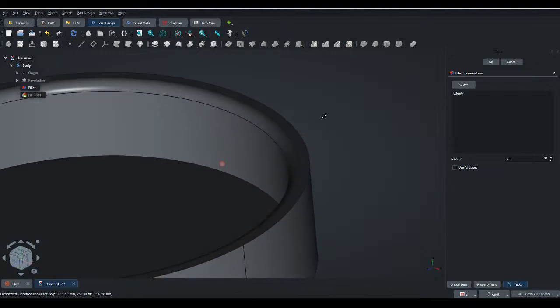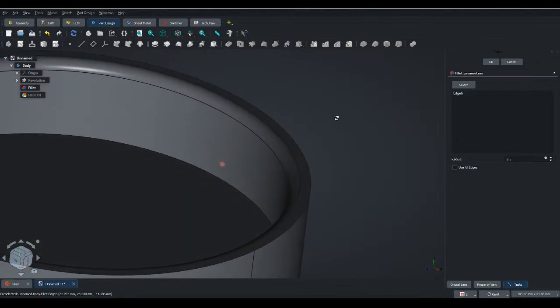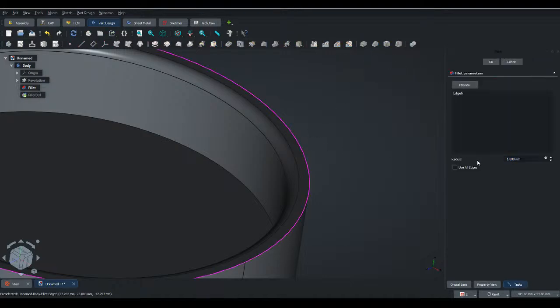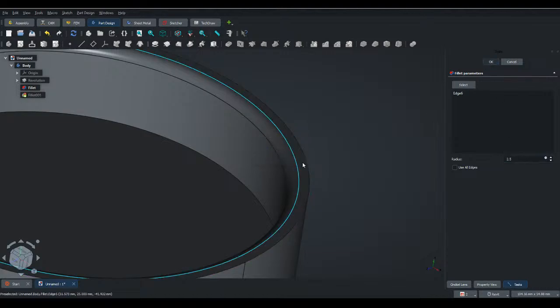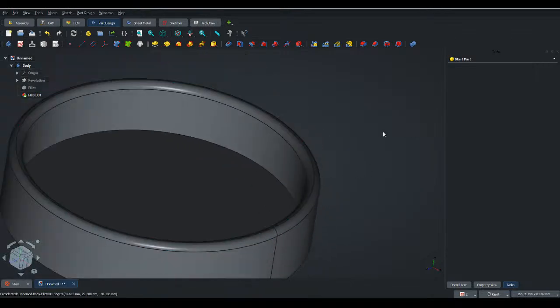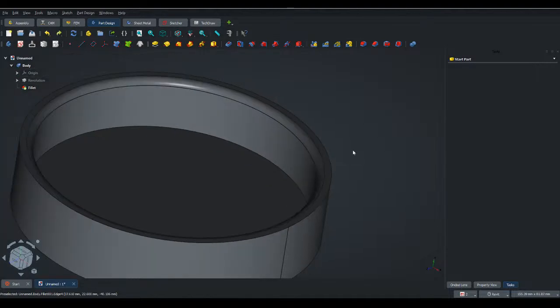Oh, okay. So when you were telling me that earlier, I know what you're having a problem with: the fillets not meeting because you went 2.5 on a 5 and they're touching. So I think you have to go 2.25.